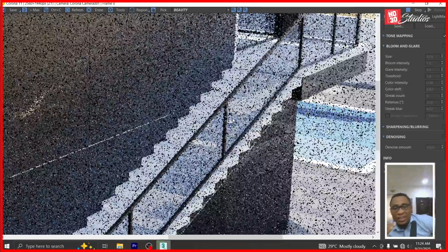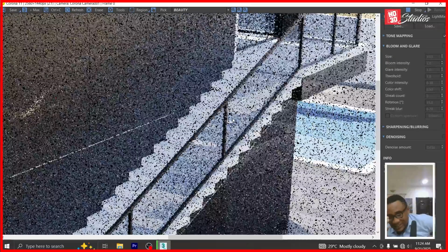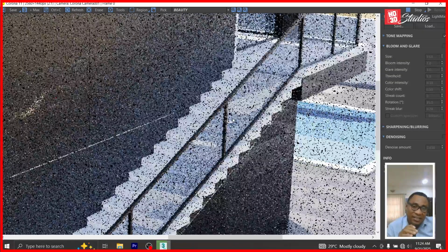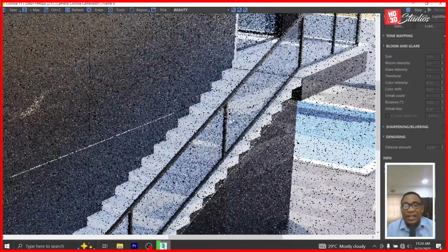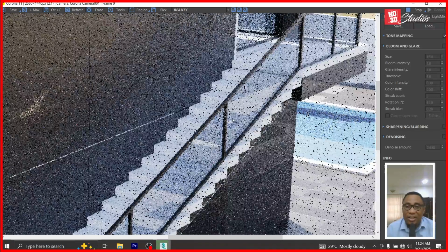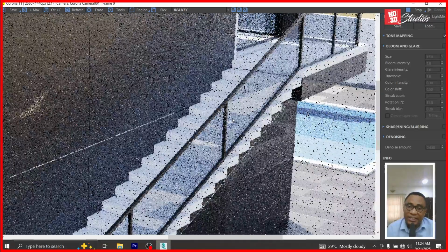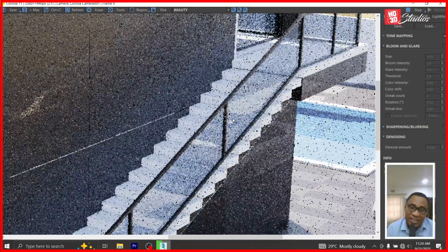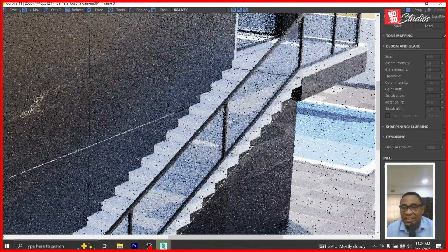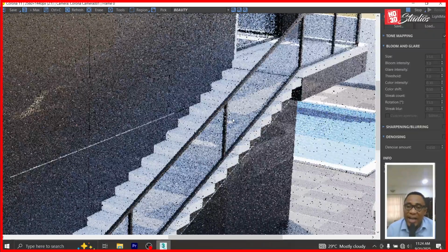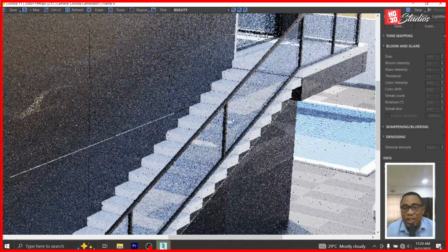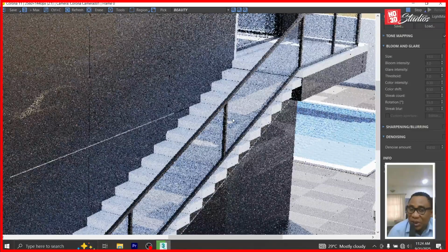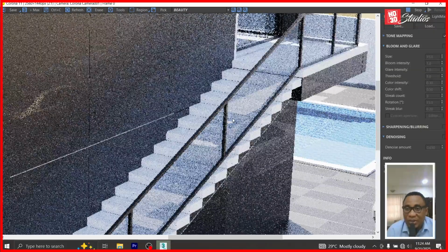We have kind of a cantilevered stair system. Each of the stairs is cantilevered by 9 inches to the right, and then there are 2 beams underneath the stairs that carry them, and then the stair landing itself also has beams, a daisy chain beam system to carry the stair landing. And then I now apply the marble texture to the stairs.